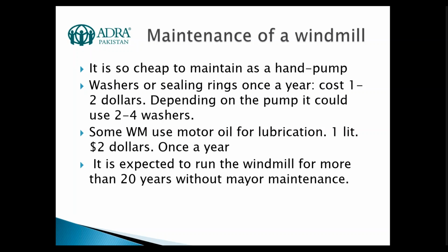Okay, talking about the maintenance, we talked a little bit, but it's so cheap to maintain a hand pump. You need to change only the washer or the sealing rings in the cylinder with the piston and valves. That could be $2. We are talking about Pakistan. It's only the sealing. It's very cheap. The community can do the change, and then it's very, very cheap to maintain.